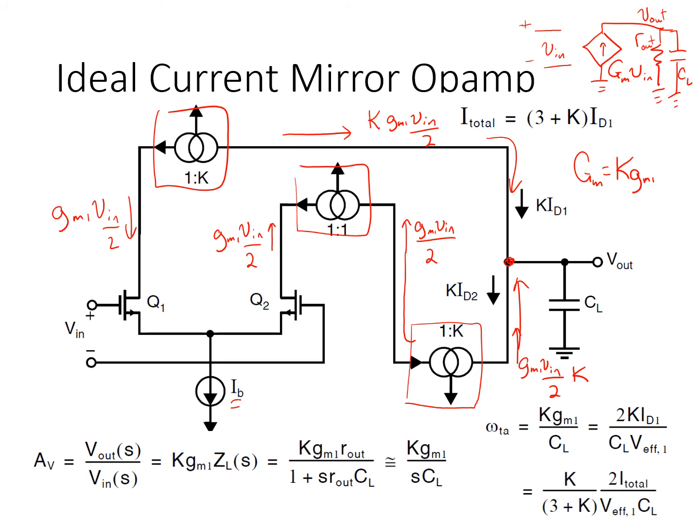So it's a single stage amplifier because if you consider the circuit node by node, you will see all nodes except for the output node are connected to the input of a current mirror. And the input of a current mirror sees a small signal resistance of 1 over gm. So the only node here with a high small signal resistance is the output node here.